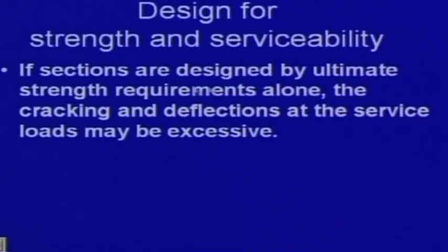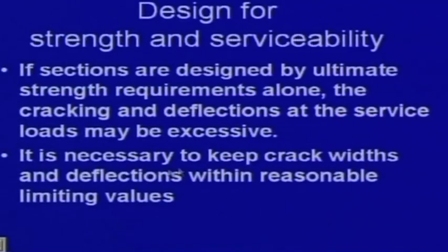So, if sections are designed by ultimate strength requirements alone, the cracking and deflections at the service loads may be excessive. It is necessary to keep crack widths and deflections within reasonable limiting values. That is obviously based on experiments: if the crack width or the deflection is this much, then we shall not feel any discomfort, and the users will not be panicked.